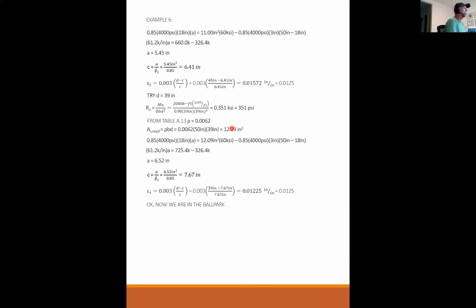Whichever loading schemes create those 2 points, those 2 points then become your design Mu. And they're different. One design Mu is for the bottom of the beam in tension. The other design Mu is for the top of the beam in tension. Does that help?